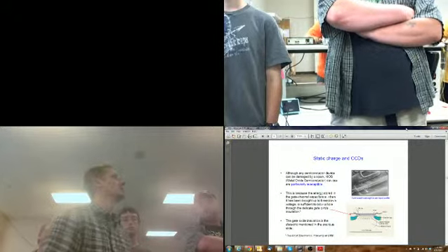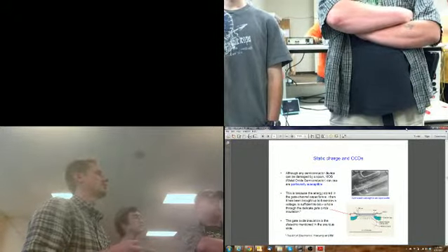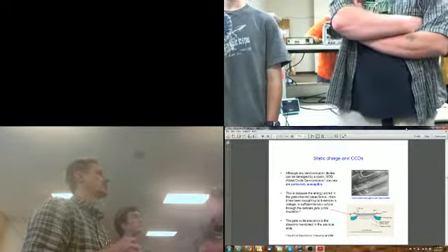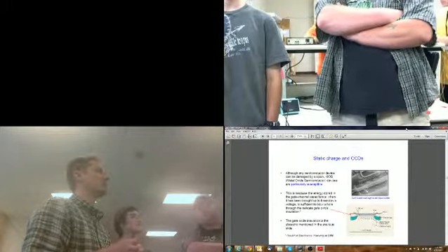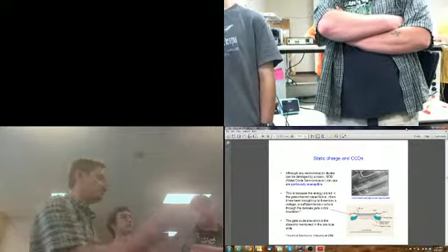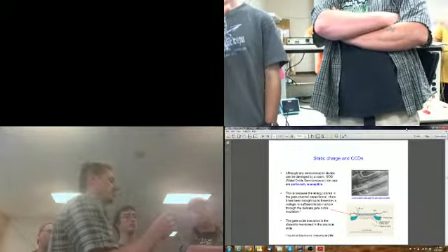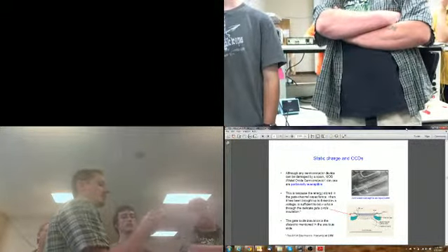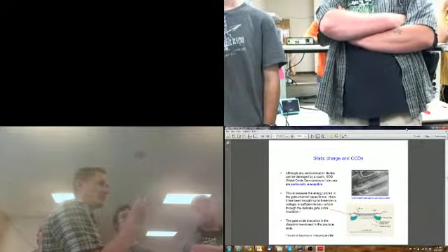So how many of the ones that we have here do you think are destroyed? 80%? 80% of them are already destroyed? Oh no, they're not already destroyed. The reason they're not destroyed is because they put ESD protection diode clamps inside of here.